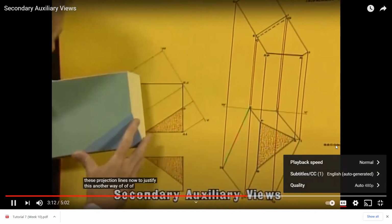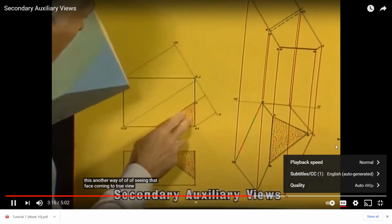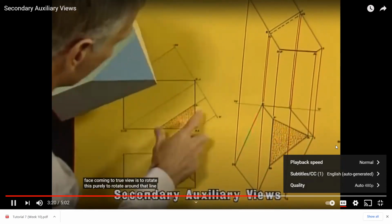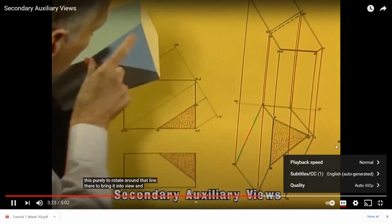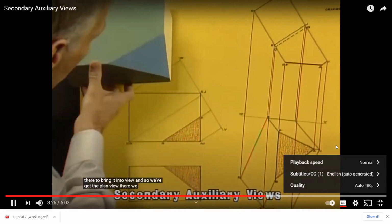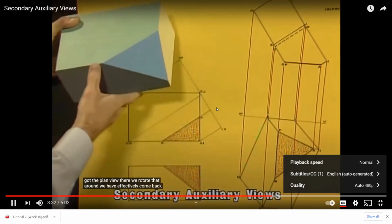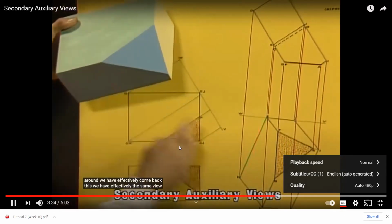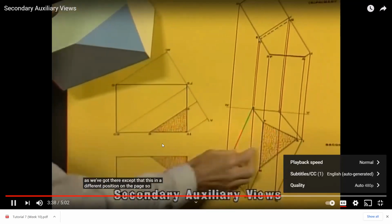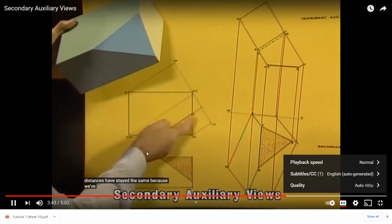Now, to justify this, another way of seeing that face coming to true view is to purely rotate around that line there to bring it into view. So we've got the plan view there. We rotate that round, and we have effectively the same view as we've got there, except that this is in a different position on the page. So these distances have stayed the same because we've rotated back the line BF.